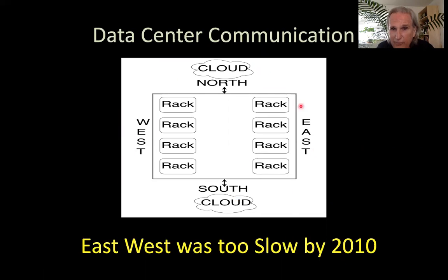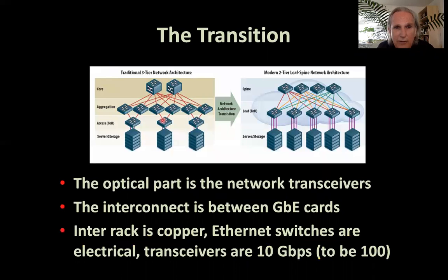The original data centers haven't changed too much in size. They have up to 100,000 racks, but the original ones were using 1 gigabit per second VCSELs on multimode fibers to hook together the racks and to go across the data center. This is telecom in, telecom out. And this was so slow that already by 2013, it required a major change.